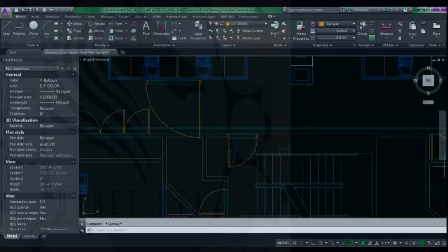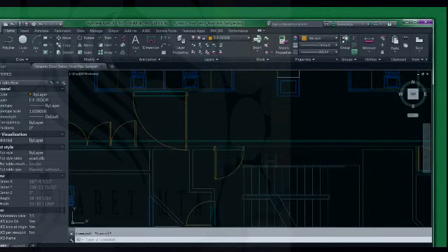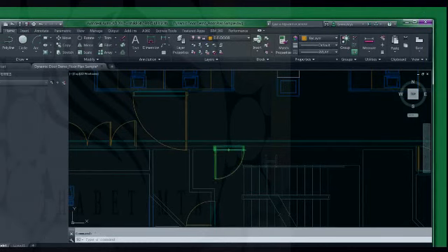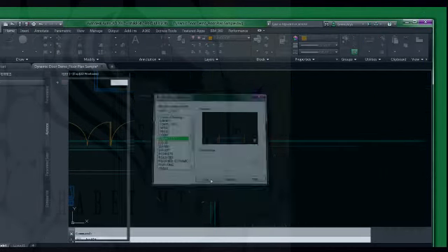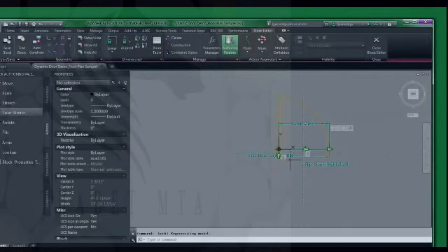Before you turn it over to me, one thing that I noticed that I want to highlight is that as you added parameters and actions, the block started to get really complicated, and you made sure to name all of those parameters. That can be so important because these get complicated very quickly, and if somebody else goes to modify your block, having those things labeled saves you a lot of time. So flip door in and out describes exactly what that parameter does. That's really important if you're sharing these blocks with other people.